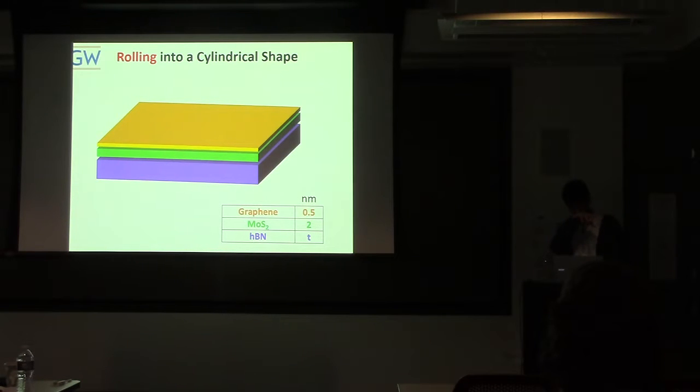So we thought of a model to absorb a significant amount of light, up to 90%, and really not make it too complex, not need many buffer layers, many contacts for each of these layers. So the platform for it was a monolayer graphene as a contact, molybdenum sulfide as a photoactive material, a photoabsorber, and HBN as an insulator and a platform.